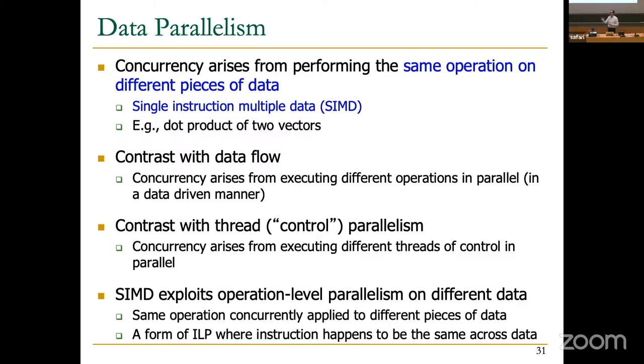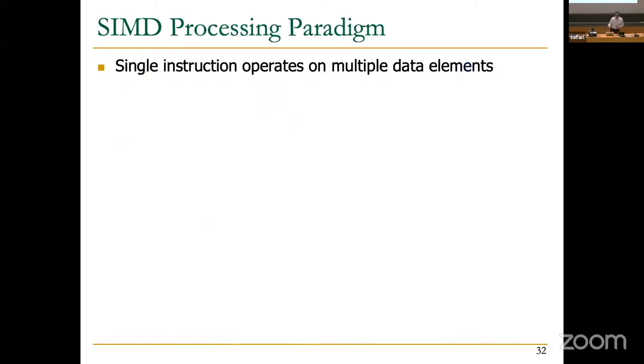You basically don't waste time figuring out, oh, I'm doing this operation. Basically, you know that you're doing this operation on 1 billion data elements, so you're not going to waste time figuring out what you're going to do to all of those elements. You're going to do that only once. So you're basically amortizing the cost of control because you're doing the same thing across billions of elements, right? So that's the beauty. If your vectors are larger, this becomes more efficient, as you can see, right? If your vectors are smaller, this starts resembling a scalar processor. In the limit, if your vectors are size 1, meaning a single element in each vector, this is a scalar processor. Right?